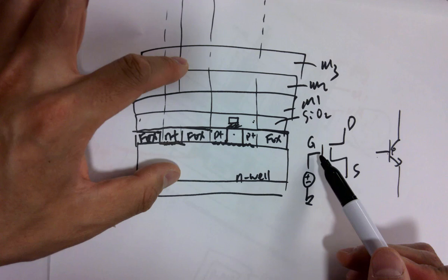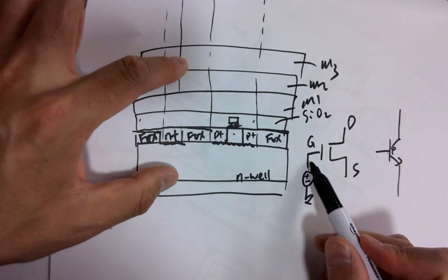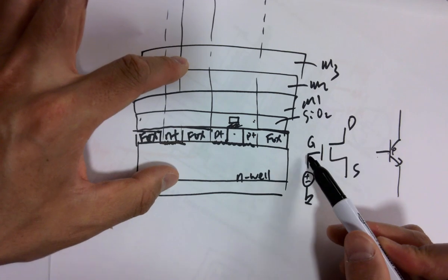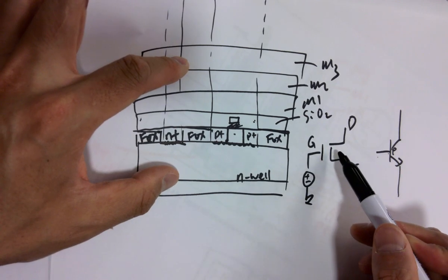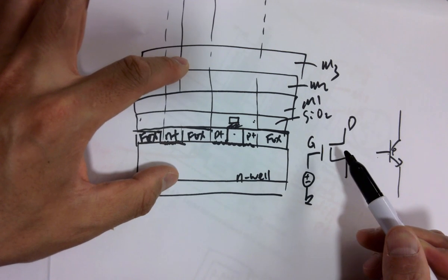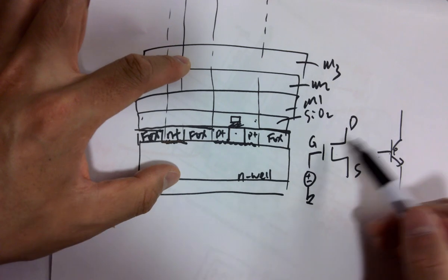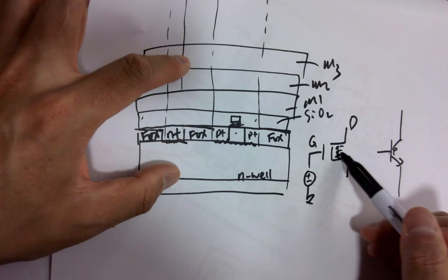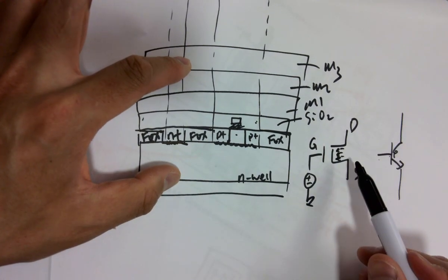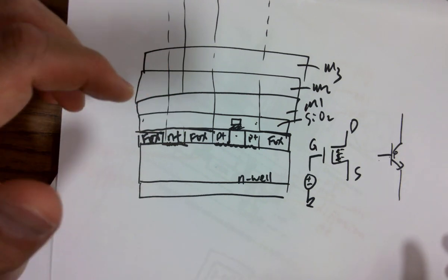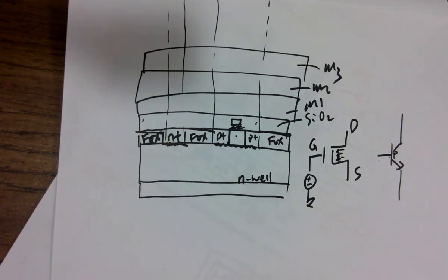So the way that works is, whenever you apply a positive voltage at the gate, it's creating an electric field instead of directly injecting current into the channel. We don't want that to happen. I'm going to explain that to you in, I think, Friday's lecture. So that's how that works. It's creating an electric field to attract electrons in the channel. So the electrons are actually making up a channel. It's not conducting, but it's attracting electrons to form a channel, a layer of electrons.